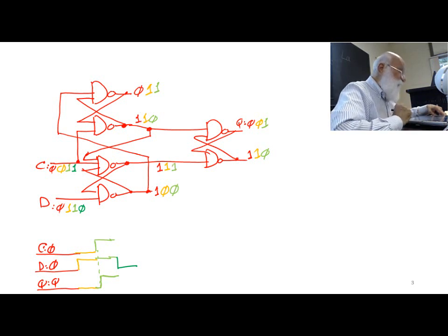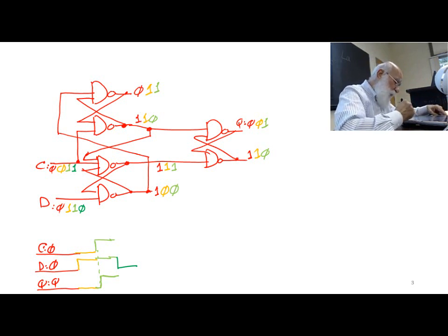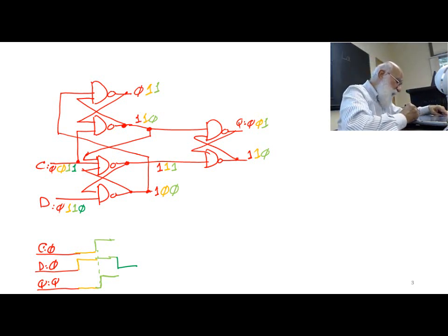Okay, this is my fourth value, and therefore I want to make sure that all the nodes have the 3 values already. So the fourth value comes in, and D is 0. D is 0 changes this gate. The upper gate of it is a 1 and a 0, so this becomes a 1. And this input, this is the only place it goes, so the 1 on this gate goes into the upper gate. So I have a 1, I have a 0, and this remains a 1.